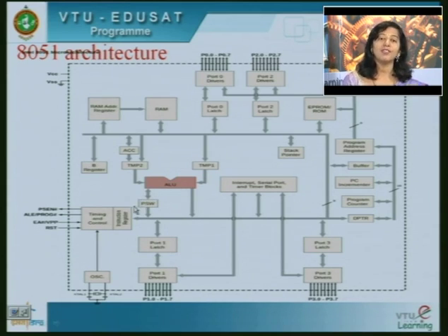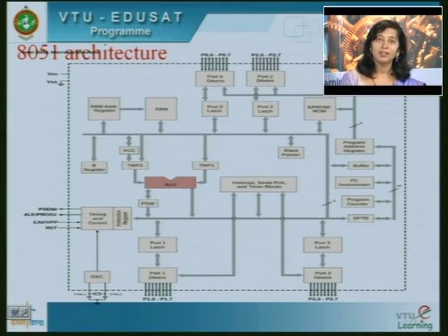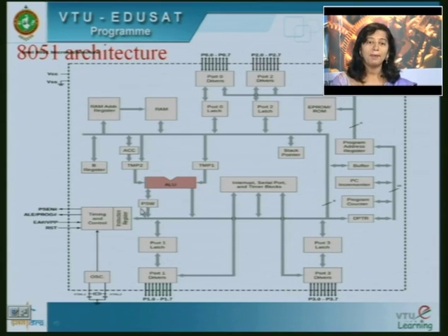So after addition, if there is a carry, the carry flag can be made high. If there is an overflow after multiplication, so when I multiply 2 8-bit numbers, the result will be 16-bit. So there will be an overflow from 8 bits. So you have different flag flip-flops, or it's a complete flag register which has multiple flip-flops to store the results of computation. After making some computation, if some flag should be set, it is there in this register called PSW or program status word.